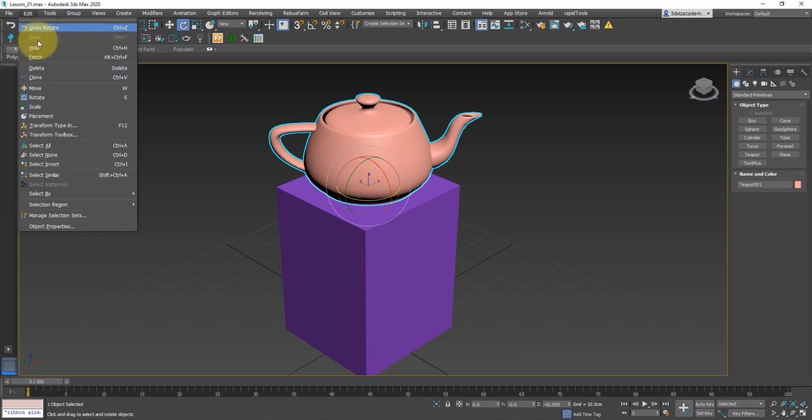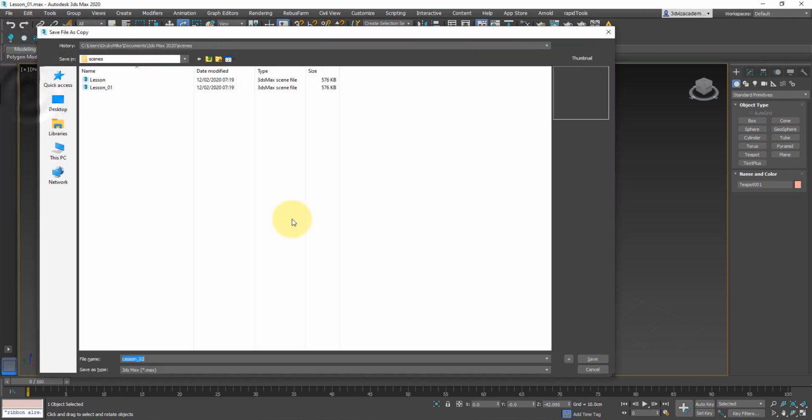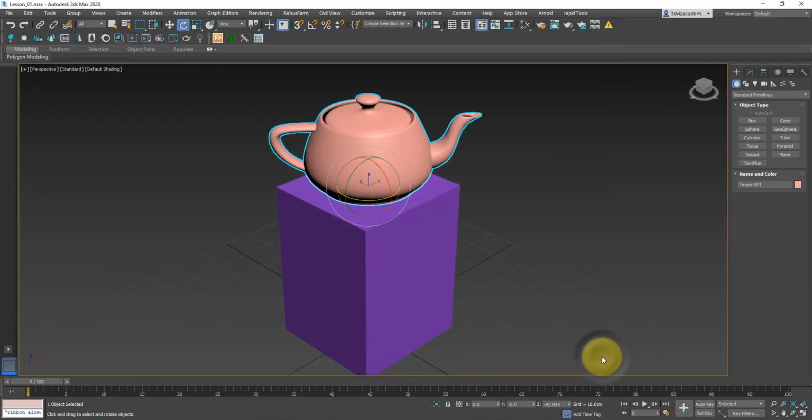If you click on Save Copy As, that means that you will be able to save your file as an independent copy, and as you can see, it's going to have a new increment number without you having to type it in. So we can just save it, and as you can see, we are still working on the previous file, file 01. That's very important in this case, because if you're going to create another override for this next scene, you may want to remember that.